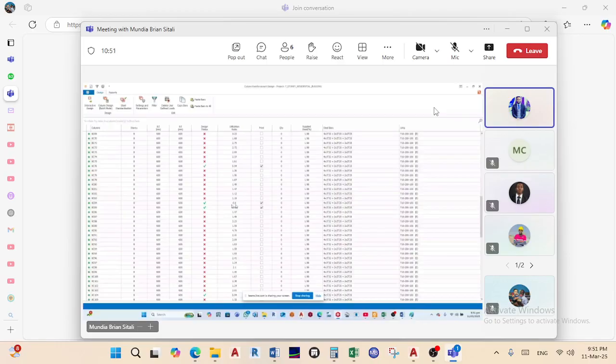Maybe try just one step up, like 700 by 700 columns, and they would work. There's a structure where I went, I think they used 800 by 800 columns. Even at 873, remember 873 in Suburb? There's some 800 by 800 columns.